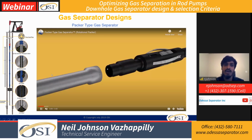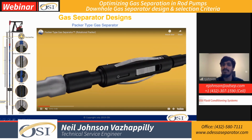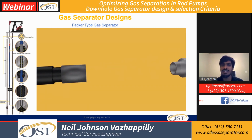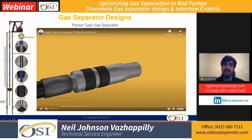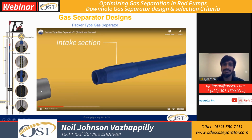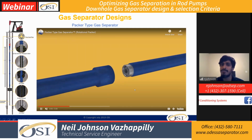We'll see now in this particular case with the rotational packer. Now that is something that we do recommend using, a rotational packer, which helps in wells with underlying conditions like chemical or sand issues. We're going to talk about it in the next few slides again as well. But this is pretty much right above the packer. We have our slotted intake. Now this slotted intake is what connects to the pump, the dip tube.